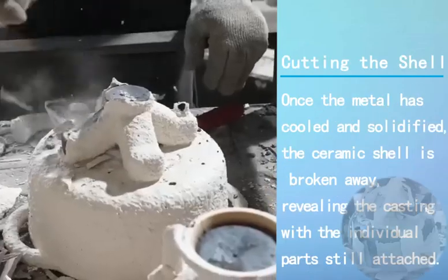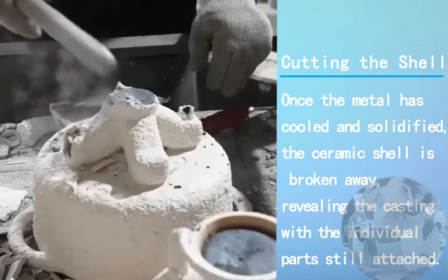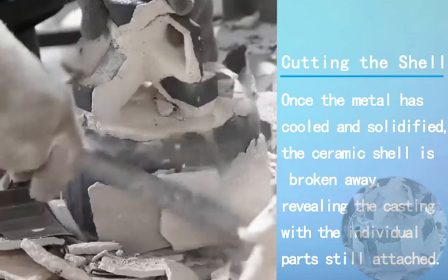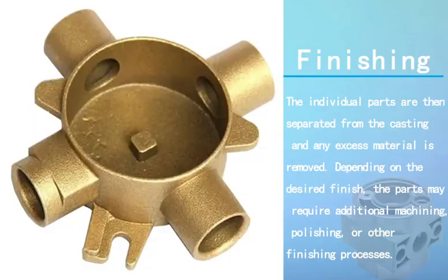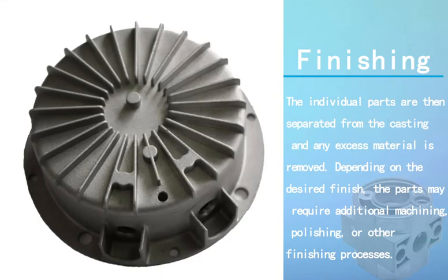Cutting the shell. Once the metal has cooled and solidified, the ceramic shell is broken away, revealing the casting with the individual parts still attached. Finishing. The individual parts are then separated from the casting, and any excess material is removed. Depending on the desired finish, the parts may require additional machining, polishing, or other finishing processes.